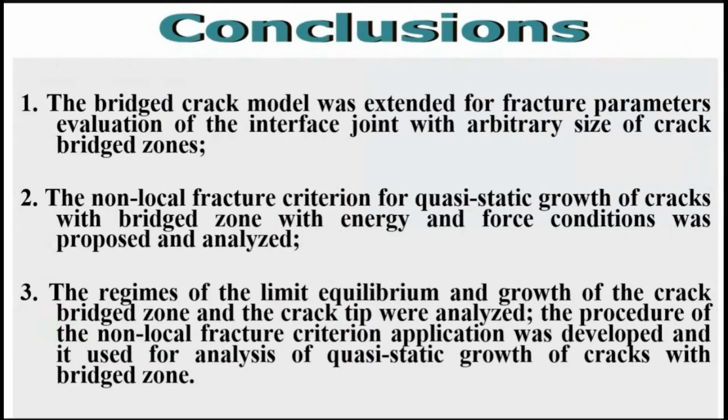Thank you. Next, please. And finally, some conclusions. The bridged crack model was extended for fracture parameters evaluation of an interface joint with arbitrary size of crack bridged zone. The non-local fracture criterion for quasi-static growth of cracks with a bridged zone, with energy and force conditions, was proposed and analyzed. The regimes of limit equilibrium of growth of the crack bridged zone and crack were analyzed.